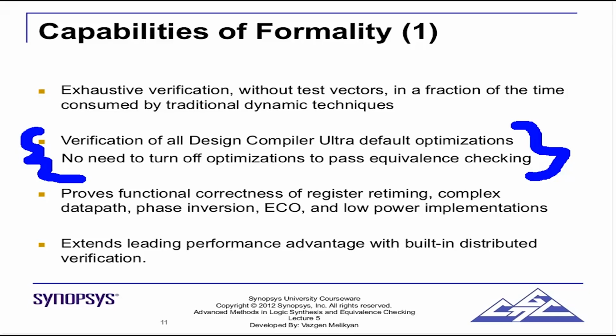Now, what many engineers would do if they cannot pass the formal equivalence between RTL and the netlist is that engineers tend to avoid such optimization steps. I have also done that in my career. We tend to avoid such aggressive optimization steps which are difficult to verify using any formal equivalence tool.